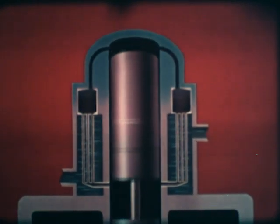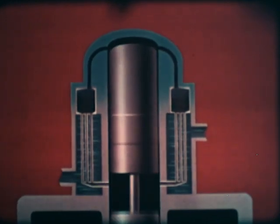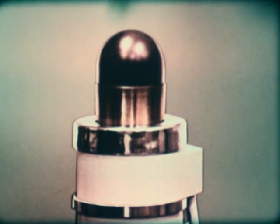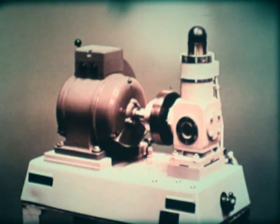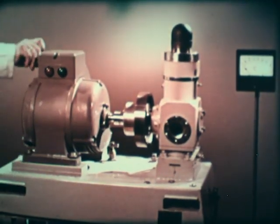It is even possible to cool the head to such an extent that the air around it is liquefied, as in the case of the famous Phillips cryogenerator. Thus, the Stirling cycle can be used as the basis for an engine or for a refrigerator, the machine running in the same forward direction in both cases. However, if the direction of rotation is reversed, 2 other modes of operation are obtained. We will demonstrate these 4 modes of operation.